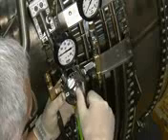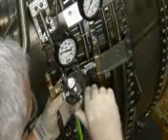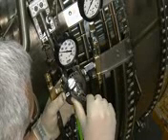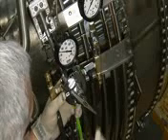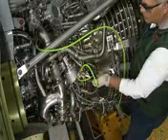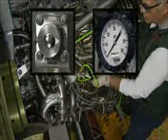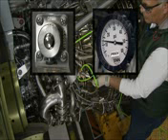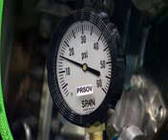Now open the regulator on the test supply assembly to provide the specified supply pressure to the bar. Check the control pressure from the bar to the PRSOV by looking at the gauge on the PRSOV test assembly, and observe the movement of the PRSOV as you apply pressure. If control pressure is low, there may be a leak or faulty part. To isolate the problem, begin with the PRSOV.